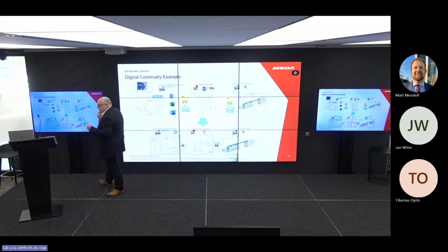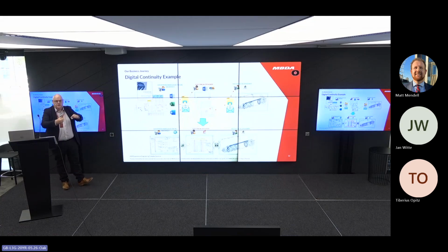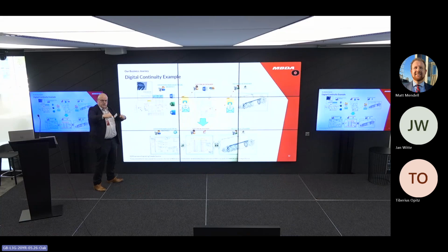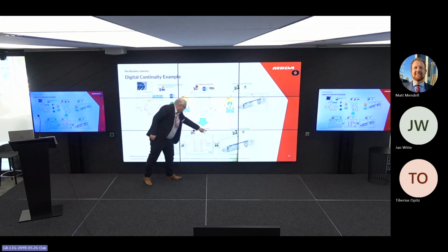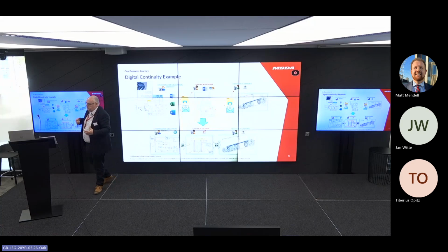Now, typically, it never works the first time. So you take the 3D picture, you go, oh, that cable's a bit too bent. You know, it's 90 degrees. That's not a good thing in cable design. So we change it, and we flow that information back along. Okay. So I just wanted to highlight that. That's where we've got to today.